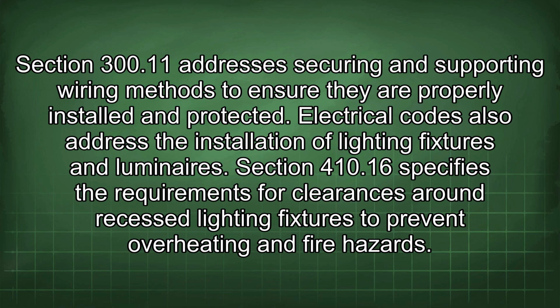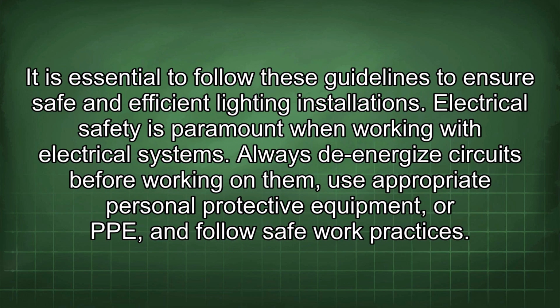Electrical codes also address the installation of lighting fixtures and luminaires. Section 410.16 specifies the requirements for clearances around recessed lighting fixtures to prevent overheating and fire hazards. It is essential to follow these guidelines to ensure safe and efficient lighting installations. Electrical safety is paramount when working with electrical systems.